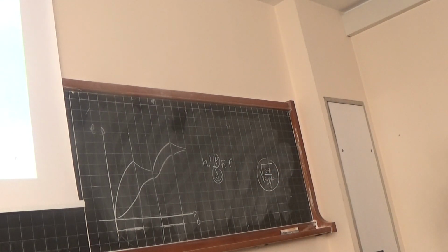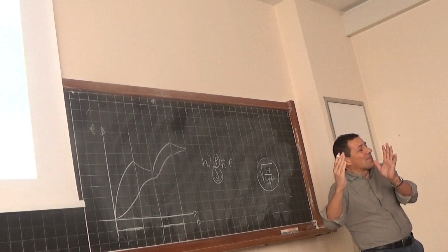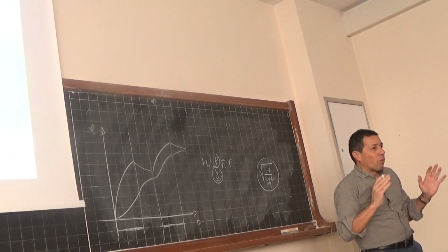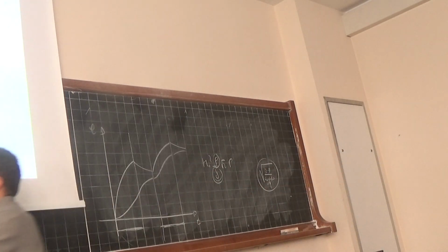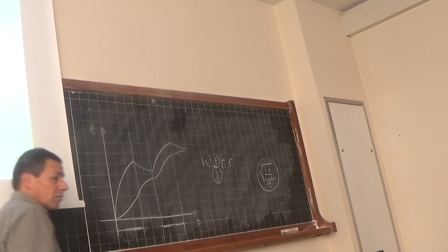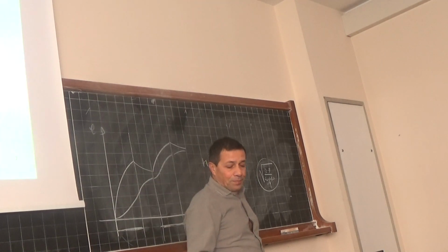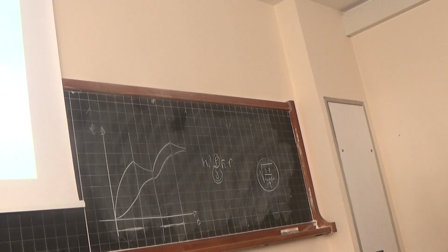So, by using a combination of inductors and space between inductors, we are able to control properly the temperature distribution in a different way, and to reduce also the temperature gap. The temperature difference in this case is not true, but the temperature difference between the surface and the axis. So, we will have such a kind of thermal transient both in a continuous movement of the billet and in a stationary one.